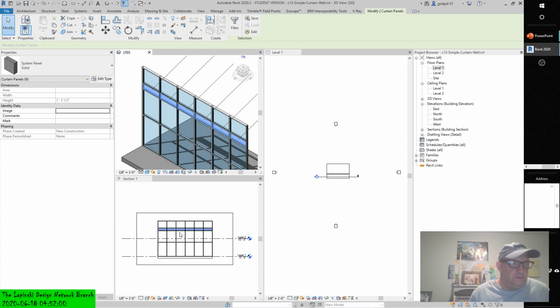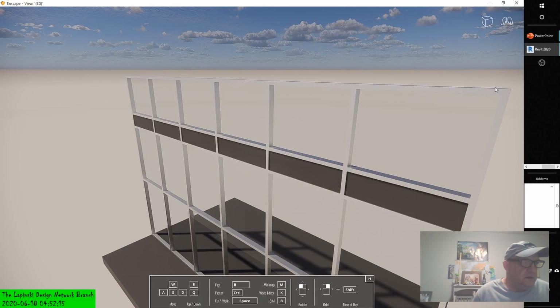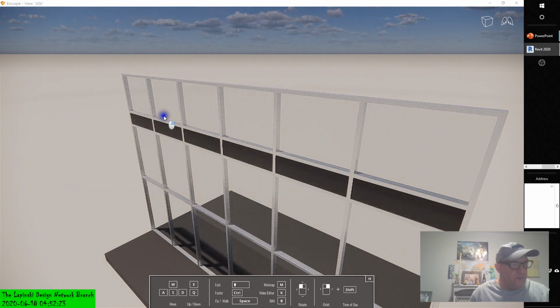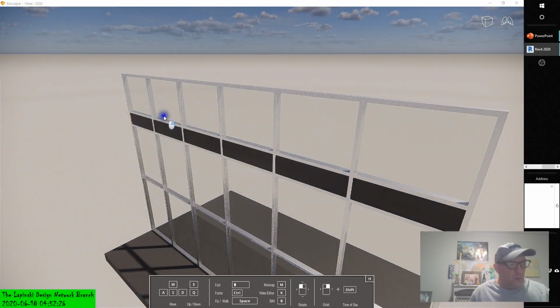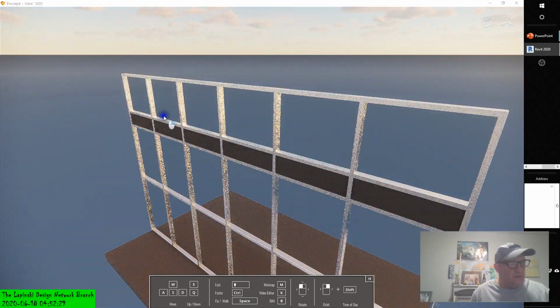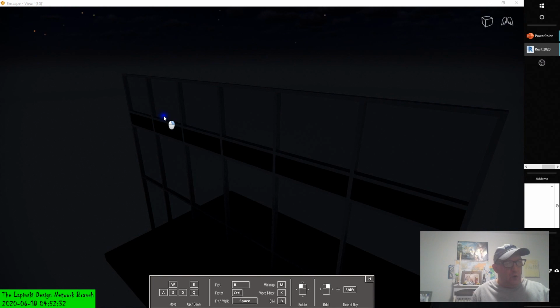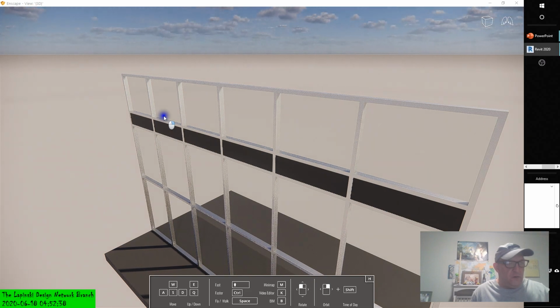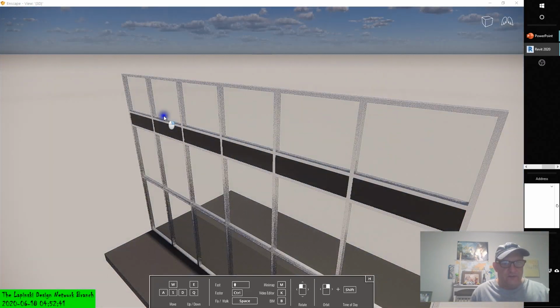Customizing curtain grid segments. In the last part of this exercise, you will practice the techniques for adding or removing segments of curtain grids to refine your curtain wall design. One important fact, this is for BIM managers. One important fact to remember when working with curtain grids is that they are always implied across the extent of the curtain wall. When we say they're implied, we mean that they are not necessarily expressed on all panel elements. In other words, although a panel grid is always expressed from one end of the wall to the other, you can decide whether the grid divides every panel it crosses.